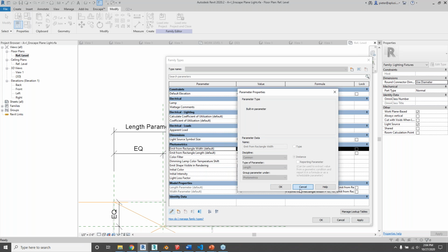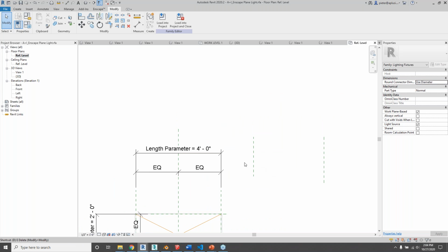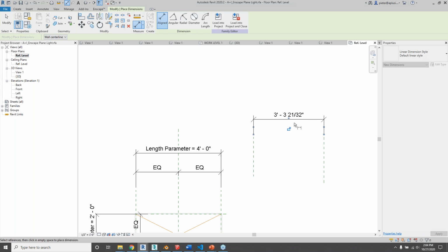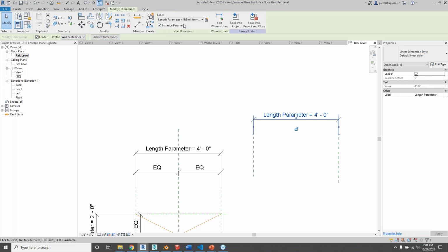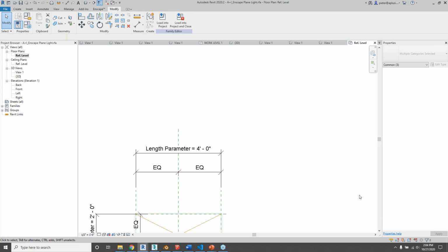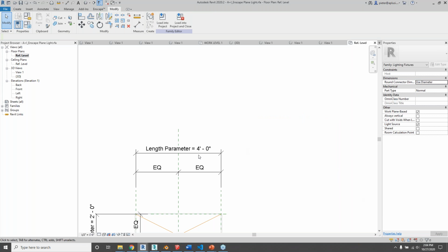It's frozen, but maybe this was a happy accident. Maybe this was on purpose. They forgot to lock it here. So here you can change it. That's a way to work around some of these parameters that are typed and you can't seem to change them. You just put up 2 reference lines, put the parameter in between them, change it, and delete the reference lines again. And it works. I've never had any issues with it.